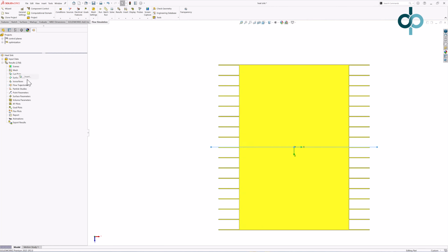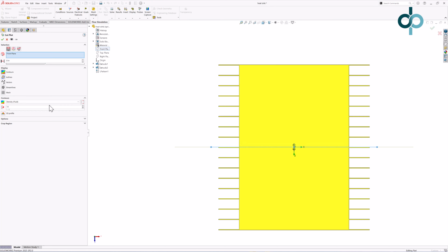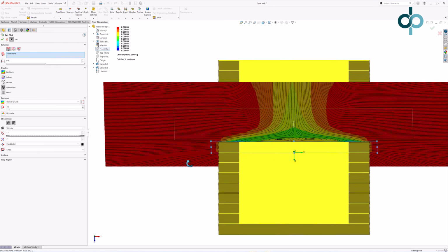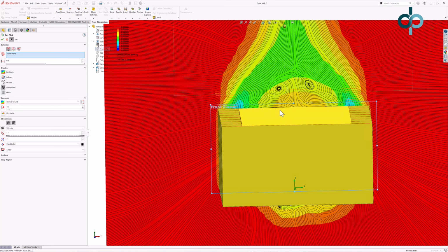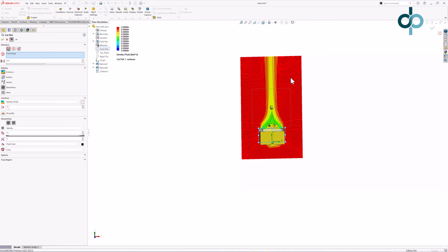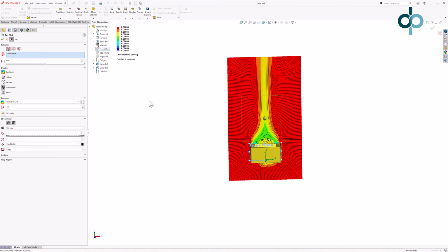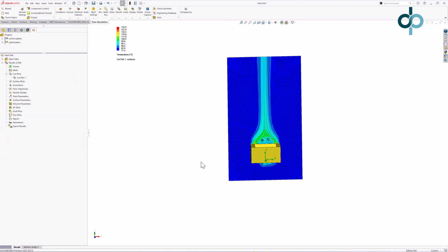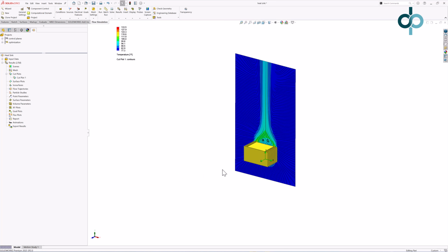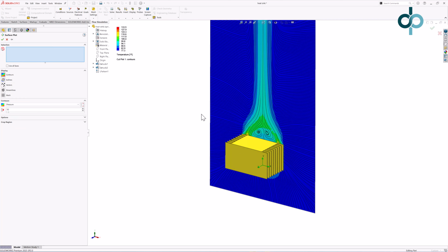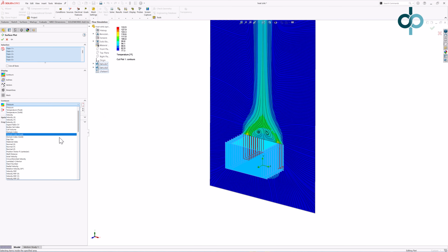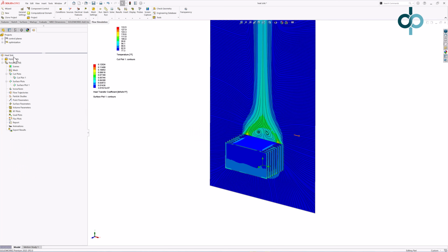First, let's visualize how the fluid flows using a cut plot, showing both velocity and density. The air is being heated by the heatsink, and as a result, the warmer air will rise. And this is all taken into account automatically because we included gravity. One thing that's super complicated with these heat transfer studies is the heat transfer coefficient. Now, this isn't a required input. We never keyed it in. With flow simulation, it's solved for automatically when there's heat transfer between solid and fluid, like the aluminum heatsink and the surrounding air here in this study.